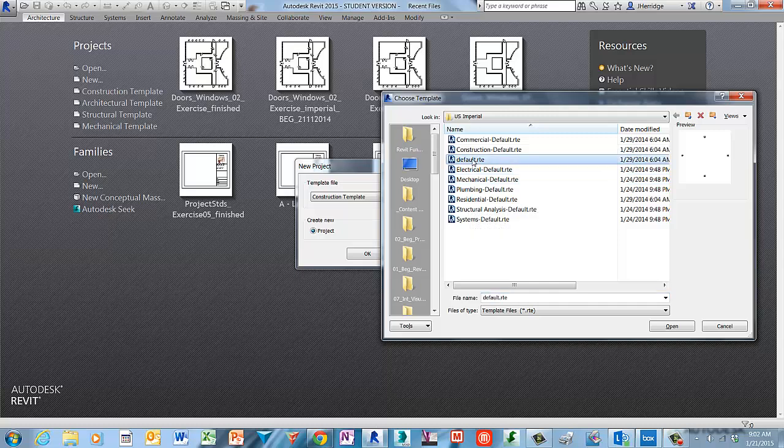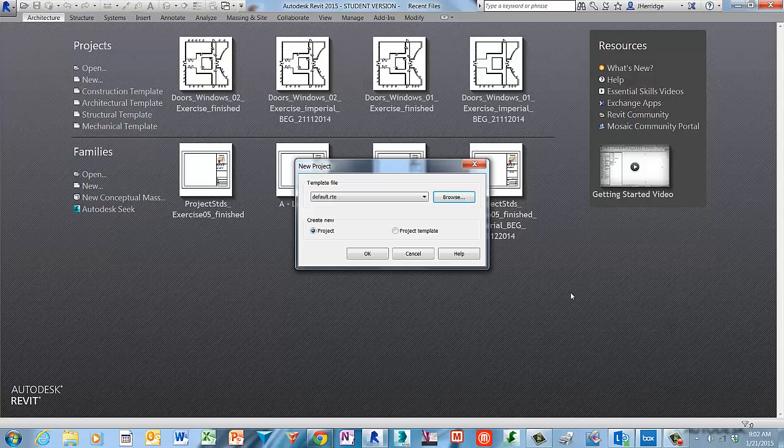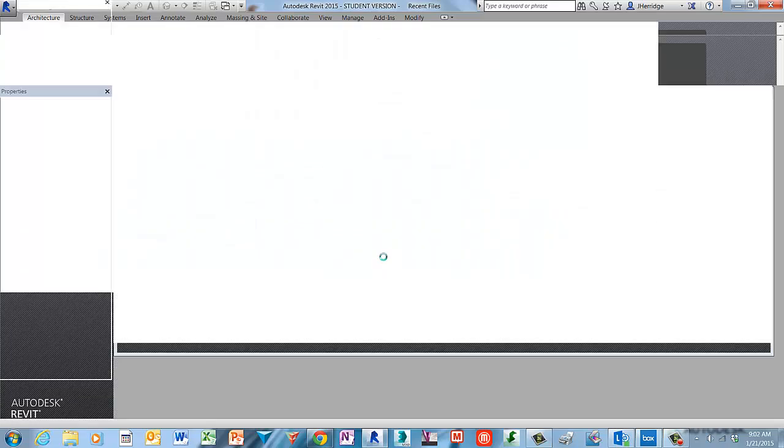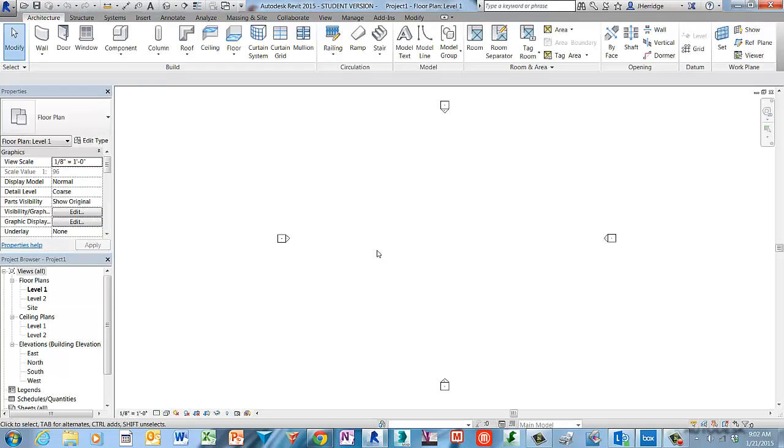So the purpose of constraints is to build intelligence into the model by defining relationships and interdependencies between elements. So what I'm going to do now is create four walls in the configuration of a rectangle, and then I will subdivide that space into 3 spaces internally.